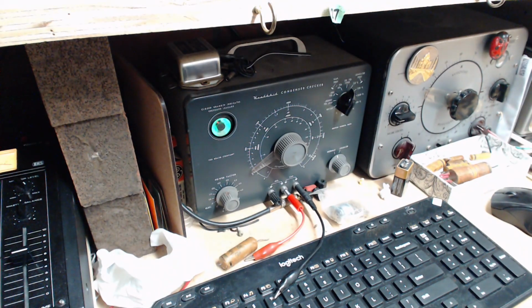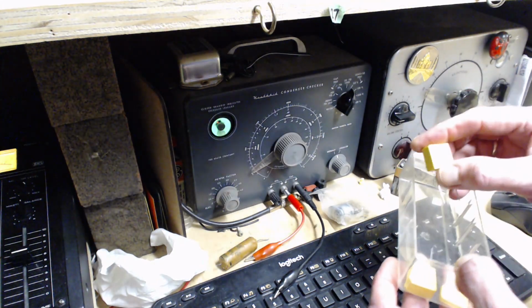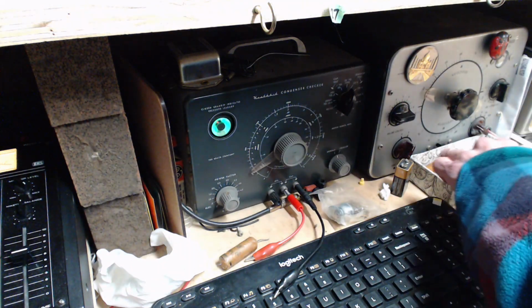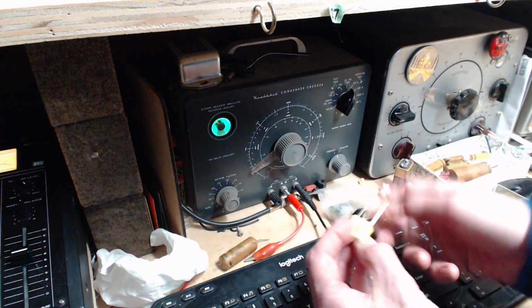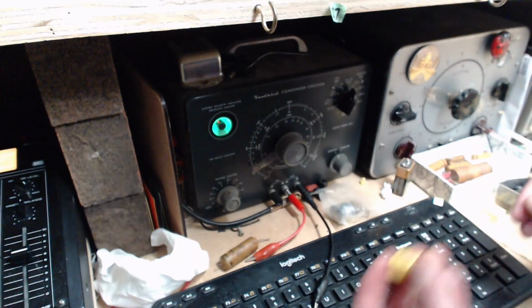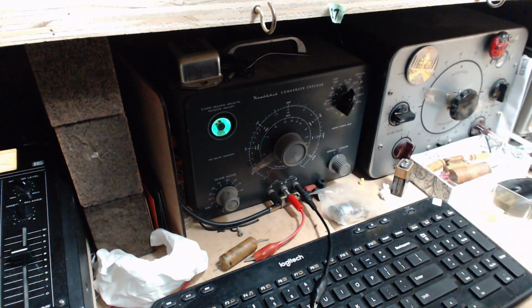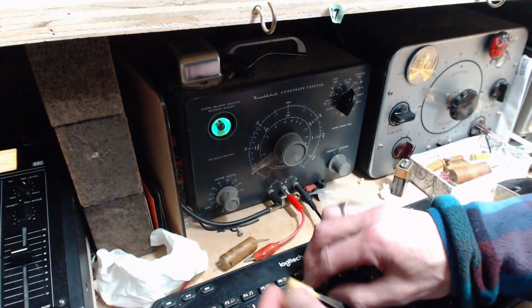And we'll grab the safety capacitors down here. There's some here. Now, 0.2, that's a big one. This is a 0.1. I don't know if I have a 0.2. Well, let's test this. Brand new capacitor. And what's the voltage? Sometimes their voltage rating is very low on these guys. Voltage rating here is 275 volts AC. Could probably take 400 DC.